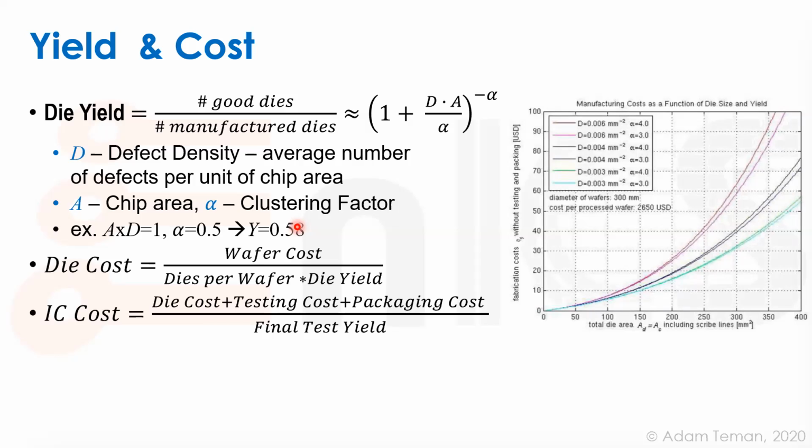It also depends very much on the nature of the die, how much memory is there, and if the memory has redundancy, because memory with redundancy is effectively zero area, since you can usually save it. The chances that there will be more than one failure in the memory are not high. So those create a more complicated formula. Okay, that's a good point.